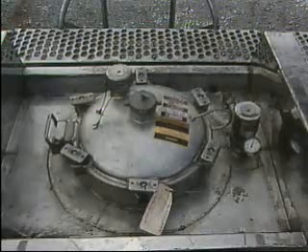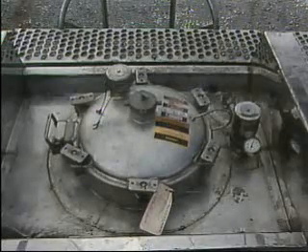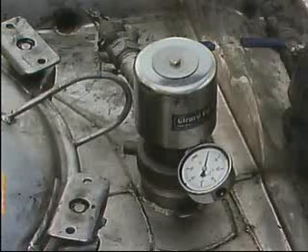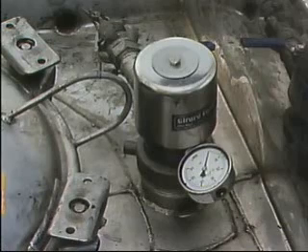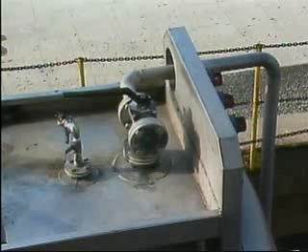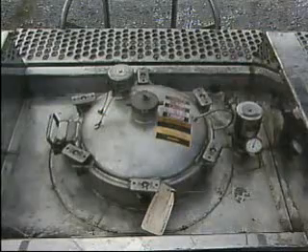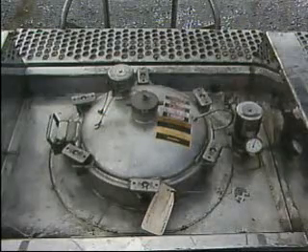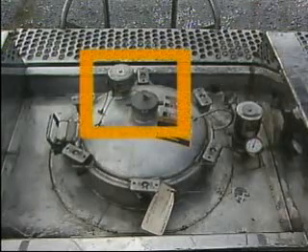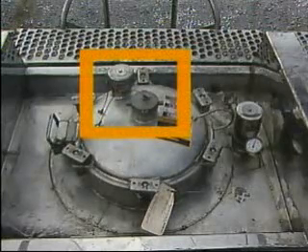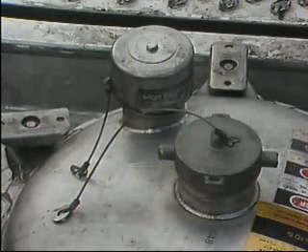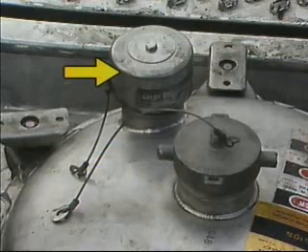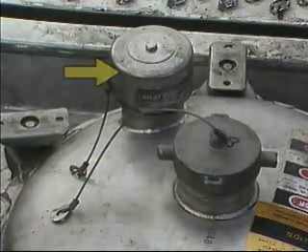At the top of the tank is a manway and a number of valves and vents. The valves on a typical tank truck include bleeder valves, which are used to bleed off pressure before the manway cover is opened, and other valves for opening and closing product lines in the tank. The sizes and number of vents on a tank truck depend on the size and type of tank. The vents can include both pressure vents and vacuum vents. Pressure vents release any excess pressure that builds up in the tank. Vacuum vents admit air to the tank to prevent a vacuum from developing in the tank.